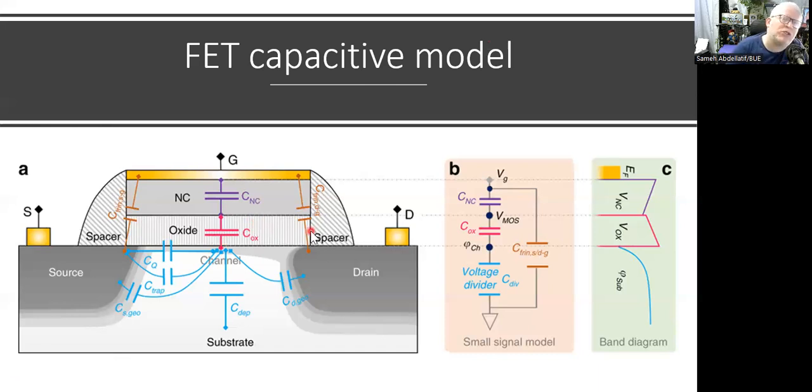When we start to measure the characteristics of a MOSFET or a FET, the process starts by scanning this transistor under various biasing conditions. For example, we will fix the VGS and we'll start to scan the VDS. And this scanning is some sort of a frequency signal, because you are changing the signal with a periodic frequency. Herein, the capacitance effect may play an important role in your IV characteristics behavior.